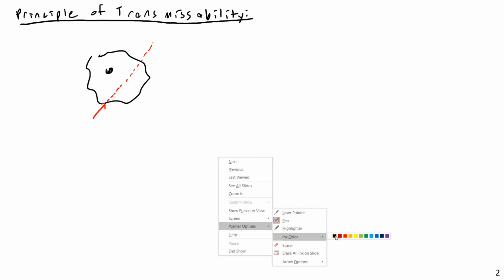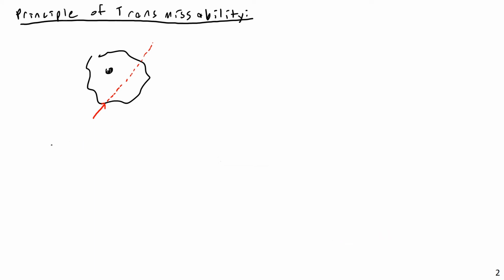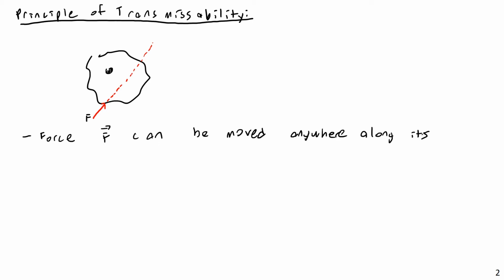So if you have a rigid body with its center of mass at some location, and we draw that force again, applied somewhere to the body, with a line of action here, what I can do, if it's useful, and I'm talking about analysis and conceptualization and math, is this: a force F can be moved anywhere along its line of action.